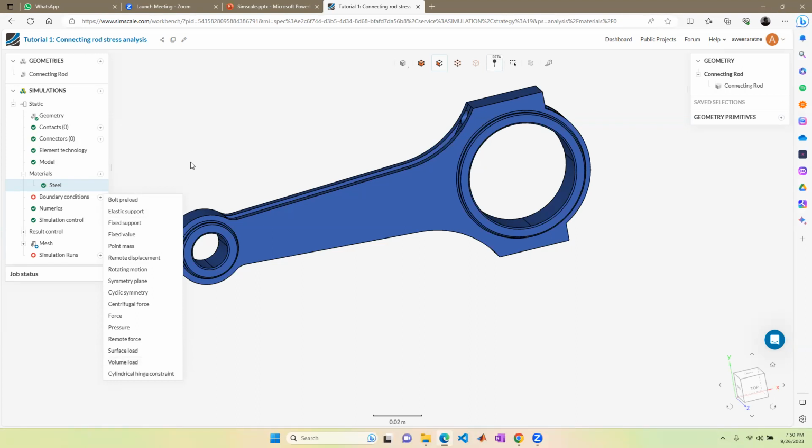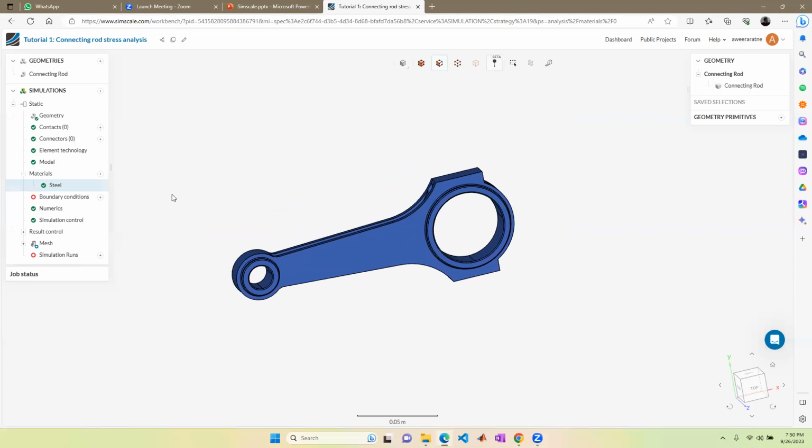Once again, I'll bring up the fact that nothing is going to prevent you from specifying the boundary conditions in an inappropriate manner and simulating some other scenario which is not actually the objective of our study. So in our case, we need to keep some boundaries fixed and a force applied to the others. In the case of the fixed boundaries, I'll be specifying it through a fixed support boundary.